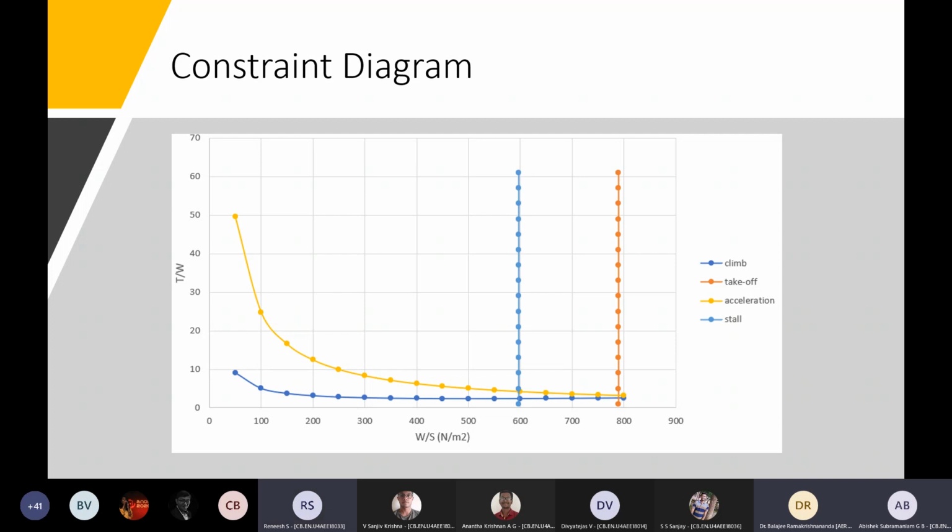Correct, the climb angle is high. You can't really use those equations. They assume small gamma. Then you have to read the equations as not assuming small gamma, and then you do those equations. Okay, that's a little bit more complicated. You can do that if you want.